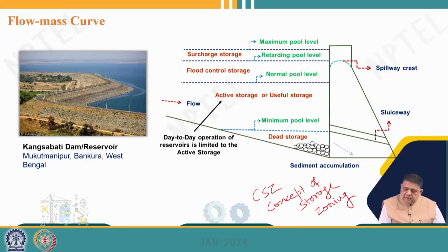At the bottommost you will find there is a dead storage, that is, a minimum pool level. This dead storage is not really useful water, it is not the useful storage, but it is provided in order to tackle the sedimentation over the life of the structure.